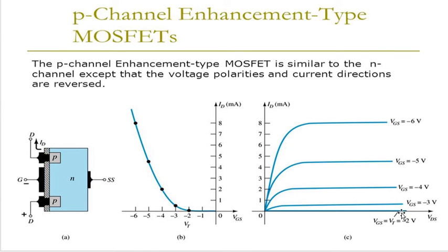So here you can see we have started providing negative signals, and when we are increasing this negative voltage, current is increasing here. So after providing an appropriate gate to source negative voltage, which should be above the threshold rating, and since gate to source voltage is negative, above means more negative, then this device will turn on.